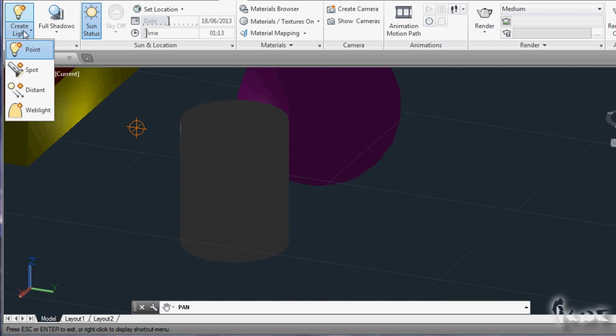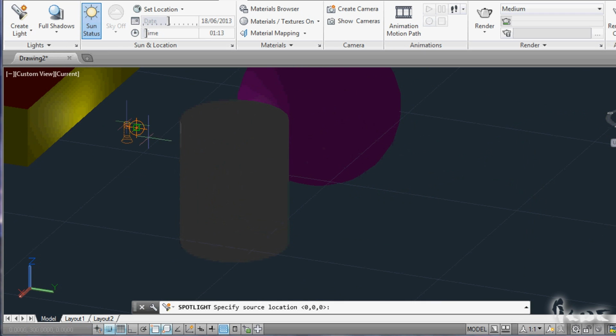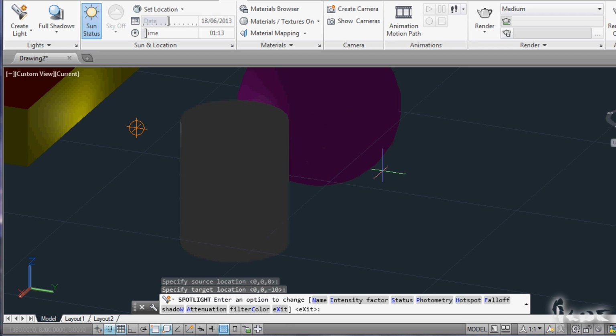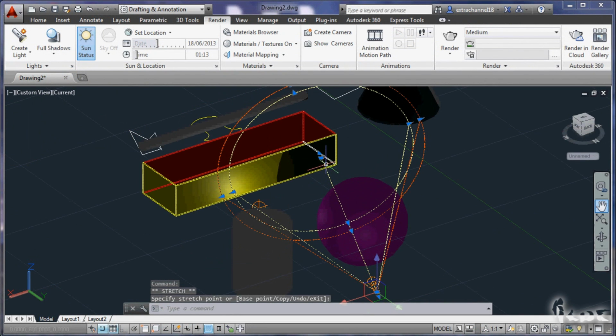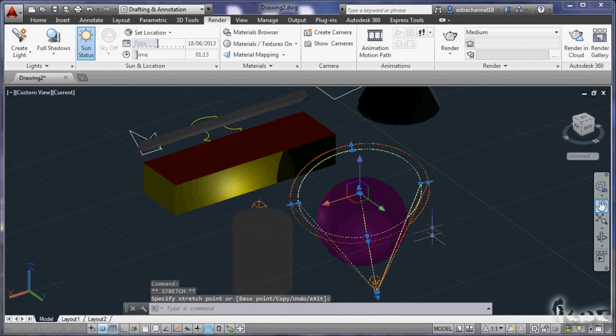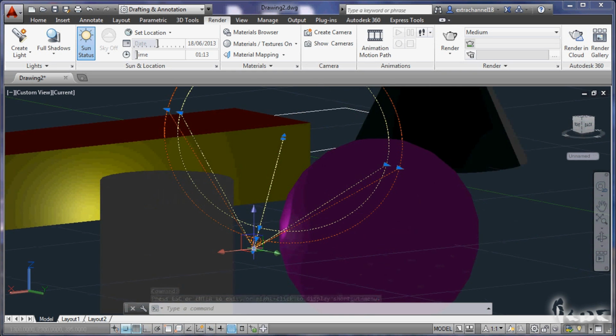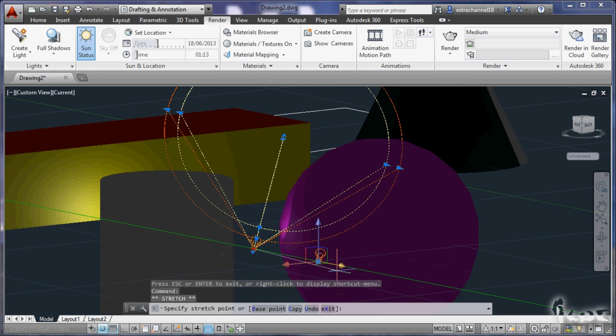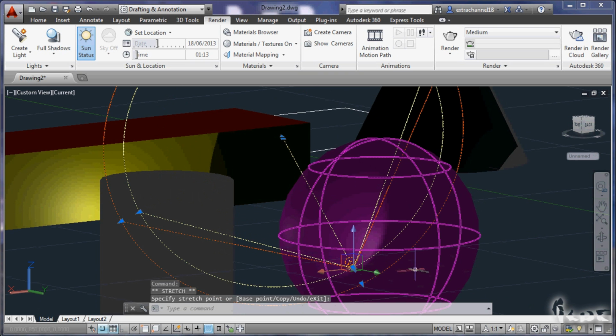The spotlight is a directed light, indicated with a torch. Firstly a placement is made, which is always made on the XY space. Then you set its direction. Then just digit X and Enter to finish. The direction of the spotlight is its target, that you can edit through the central point of its cone's base, and such stays fixed whenever you move the spotlight later.